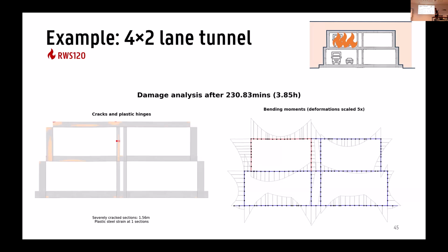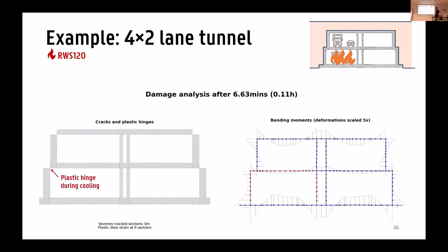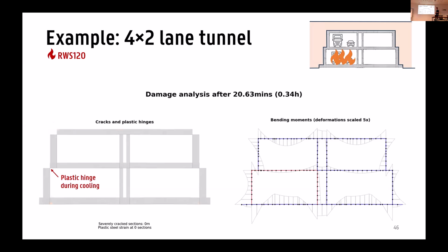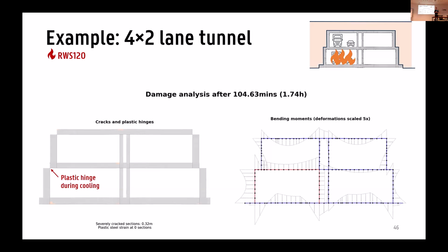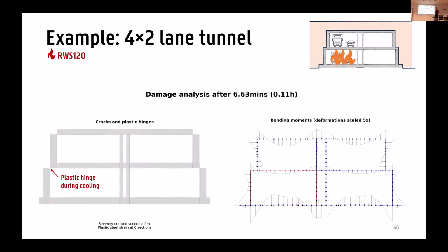Then, as a last case, we took the same tunnel, but we had fire in the bottom tube, and then we get a very different view. Again, at the beginning, cracking is very limited, but then at some point, not during the heating phase, but actually during the cooling phase, we see the formation of a plastic hinge all the way on the outer edge of the intermediate slab after about 3 hours, I think. So if you wait a little longer, we see that the moment line is again moving upwards, and then at some point we get the plastic hinge in the intermediate slab of this tunnel.